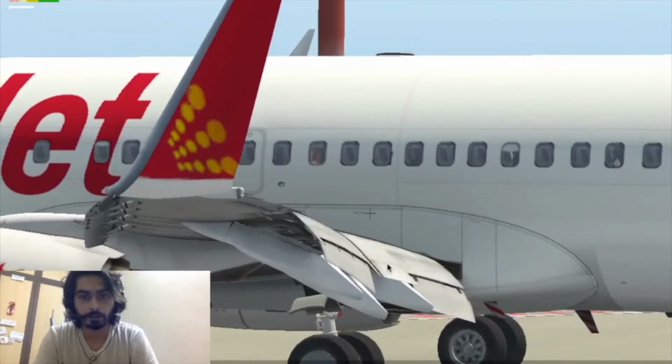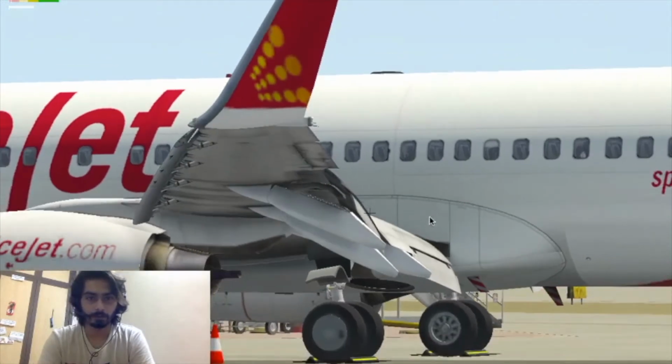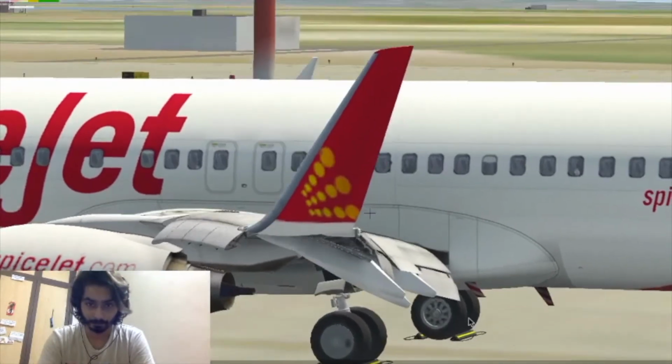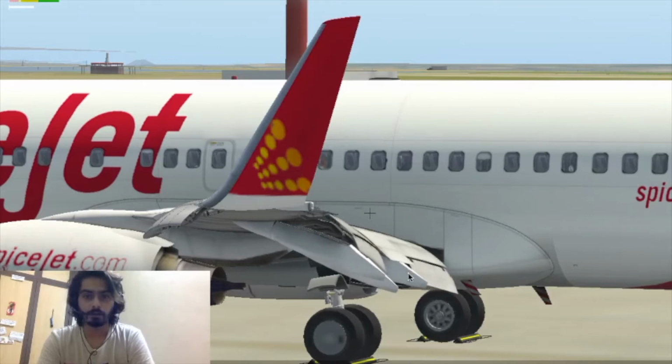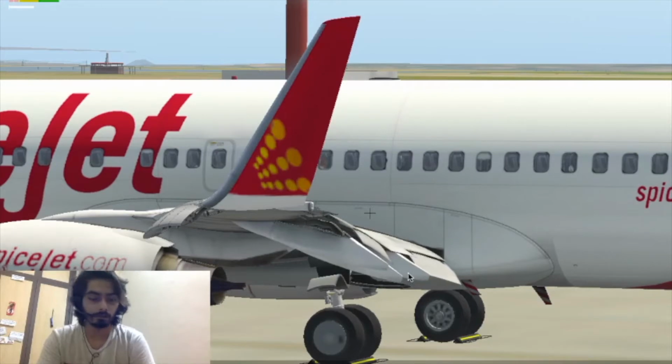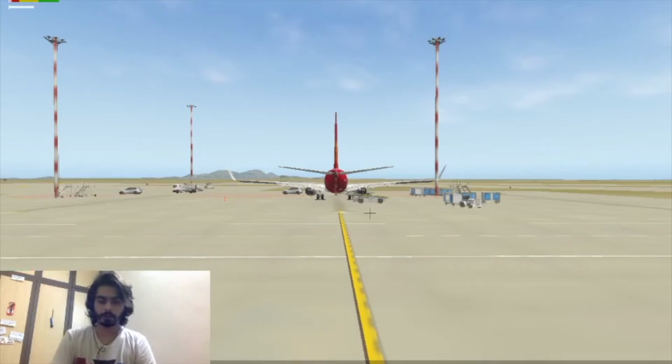Oh, no, not yet. Now this is at about 40 degrees, and see the wing which we consider to be absolutely flat, it actually changes so much of shape. If you were to see, it is almost a C, a curve right now. For now, these were just for show purposes. I'll put them back to the initial position. We'll need to start off at 5 degrees for a takeoff, but for now we are good.